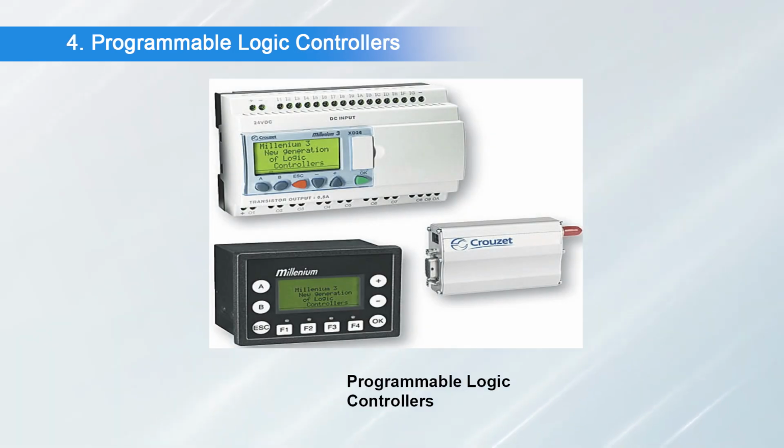Next are the programmable logic controllers, PLCs. In the SCADA system, PLCs are connected to the sensors for collecting the sensor output signals in order to convert the sensor signals into digital data format. PLCs are used instead of the RTUs we have just discussed because of the advantages of PLCs, like flexibility, configuration, versatility and affordability compared to the RTUs.